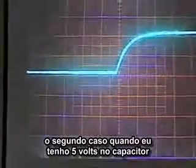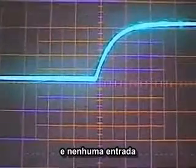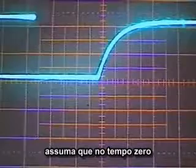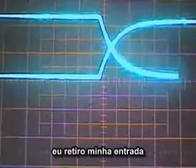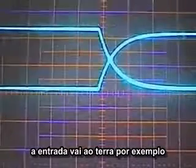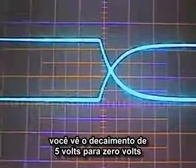The second one, where I have 5 volts on the capacitor and no input, and then I watch. So assume that at time t equals 0, I take away an input, short my input voltage to ground, for example, apply 0 volts. You see the decay from 5 volts to 0 volts.